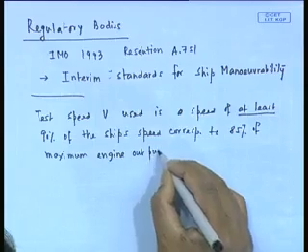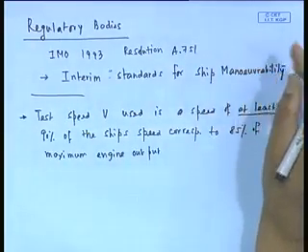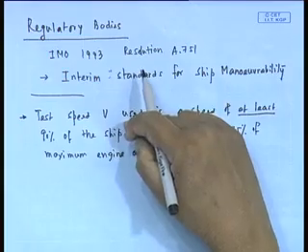I thought this is an important point. This standard will be applied at a speed which will be minimum 90% corresponding to 80% of the engine power, which means you stipulate a speed, you have to do the test at that speed, not at a very low speed or high speed or something like that.